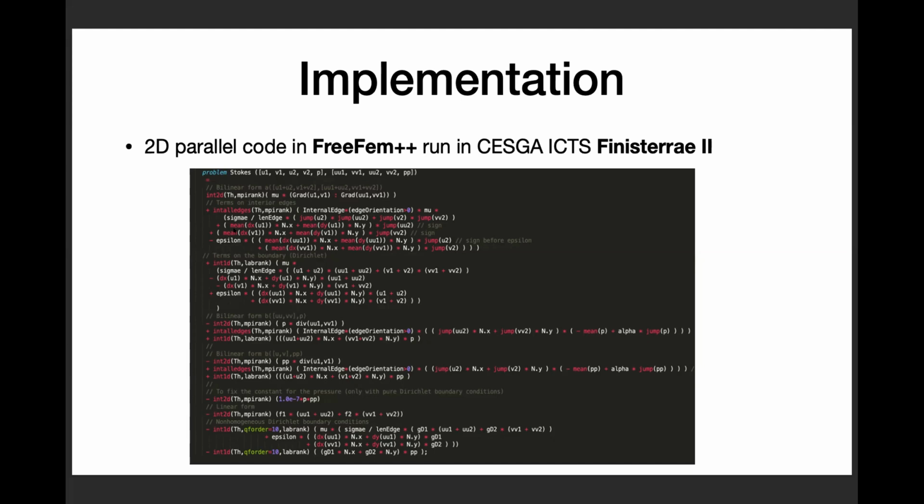So the main characteristic is that since the functions in the enriched Galerkin space are composed by a sum of a function which is globally piecewise linear and a piecewise constant, we consider two components for the velocity. So here v1 and V1 are these continuous piecewise linear functions, and v2 and V2 are piecewise constants. The pressure is piecewise constant. Then in FreeFem, there are functions to implement the averages, which is the mean function, and the jumps, which is the jump function, but the jump is not defined as in the paper. So we have some problems with this.